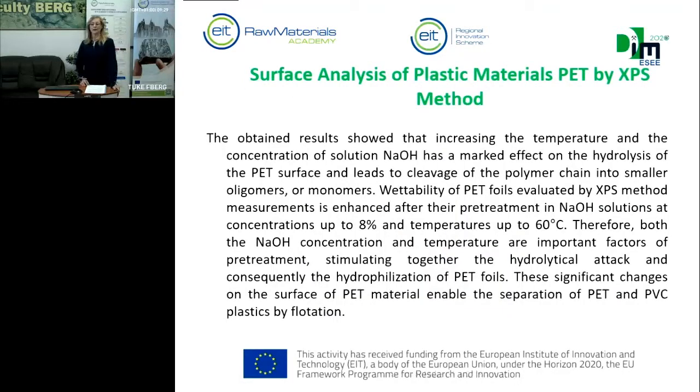The obtained results showed that increasing the temperature and the concentration of sodium hydroxide solution has a marked effect on the hydrolysis of the polyethylene terephthalate surface and leads to cleavage of the polymer chain into smaller oligomers or monomers.